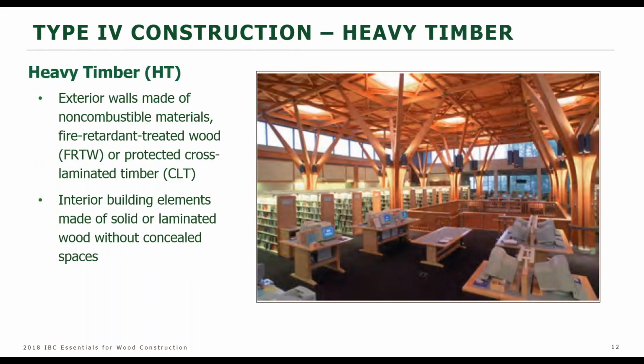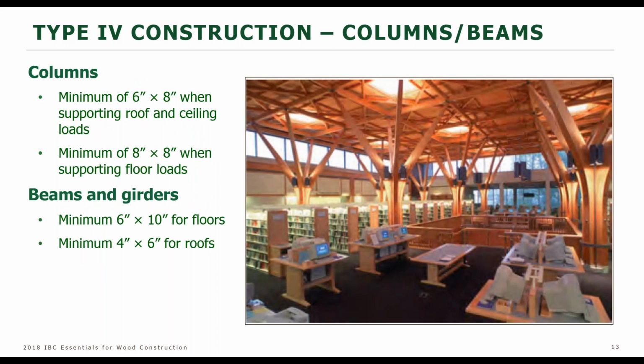Type 4 construction, I know this is review for most of you, but type 4 traditionally is heavy timber. So you have wood elements of a minimum dimension, posts and beams that make up the structural frame of the building, that can be classified as heavy timber. Fire retardant treated wood is permitted in certain locations such as exterior walls that would otherwise require non-combustible construction. Interior elements are all of wood, no concealed spaces.